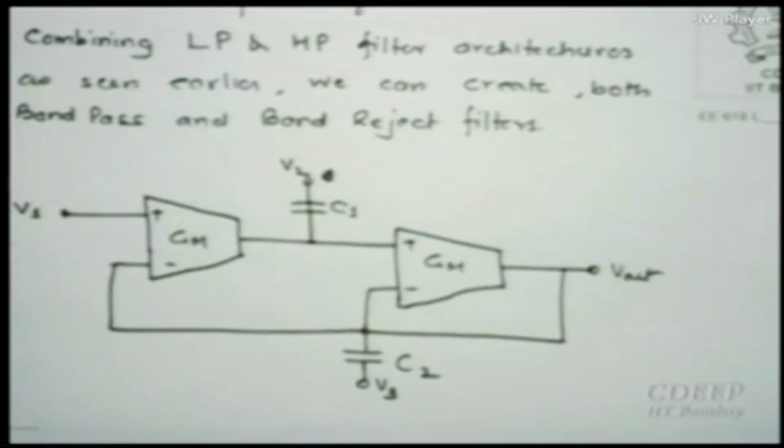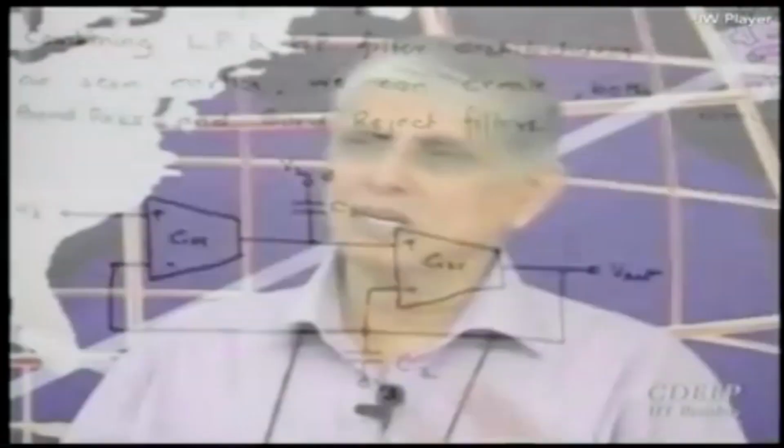And this is a typical circuit which can implement everything, that is low pass, high pass, band reject, and even notch if omega zeros are adjusted. Of course, if I only want LP, I can do one GM circuit itself, only one HP, only one GM circuit. But if I had to make three such separate chips, that's much costlier. So I will give you one chip which makes all of it. So I repeat, I can certainly have a chip only for low pass, only for high pass, but then I will have 3 or 4 chips to do each function, which I will not like.